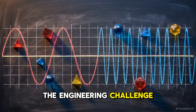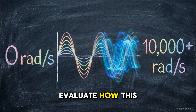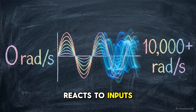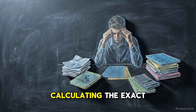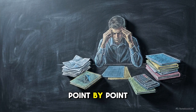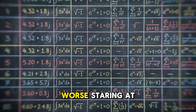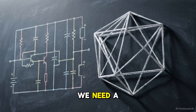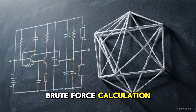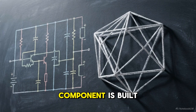The engineering challenge is that omega spans a massive, continuous spectrum. We have to evaluate how this exact system architecture reacts to inputs ranging from near zero to tens of thousands of radians per second. Calculating the exact magnitude and phase shift point by point across that massive range requires an exhausting amount of arithmetic. Worse, staring at a table of calculated complex numbers offers zero intuitive physical insight into the system itself. We need a method that bypasses brute force calculation, allowing us to instantly visualize how an architecture will filter signals before a single component is built.